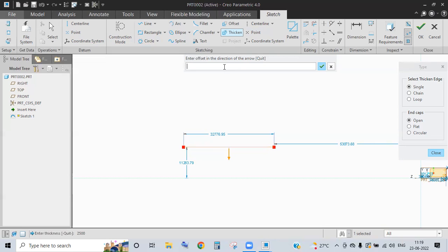Okay. What I'll say is, if you are offsetting, either it is going totally below or it is going totally up. Either it is going down or going up of the element. But I want an offset in such a way that whatever the original is exactly in the middle. For example, a line, and my offset distance is 10 and my original line should be at 5. That means I have to offset 5 below and 5 above. In offset only one line is formed, here two extra lines are formed.